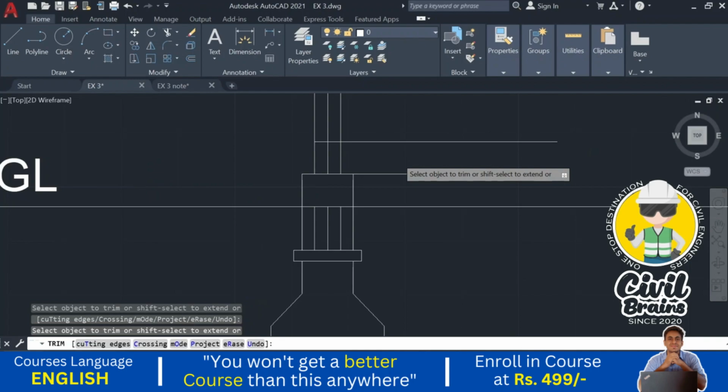Now here you can see the depth we have considered is 0.5. The width of the masonry we have considered is 0.45. But what is the width of the excavation trench for this wall? The width of the excavation trench for this wall we have taken as 0.6.